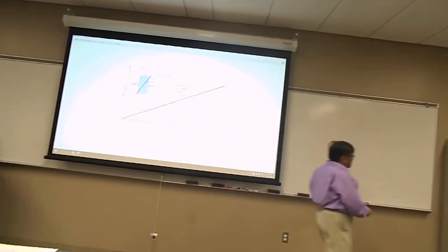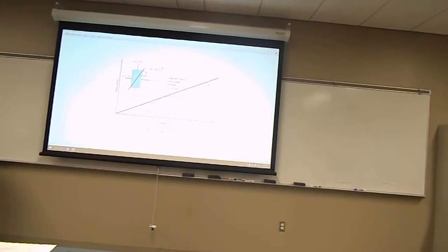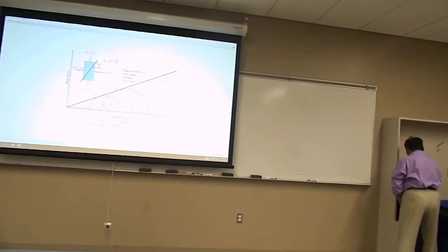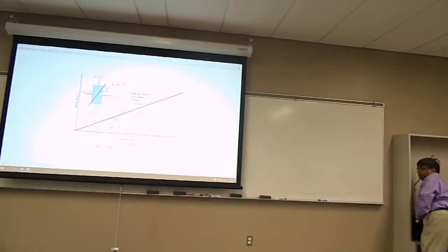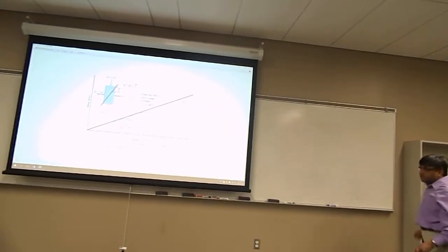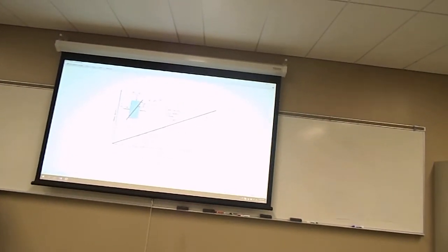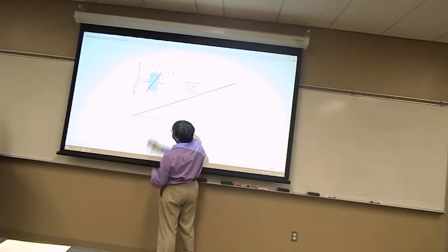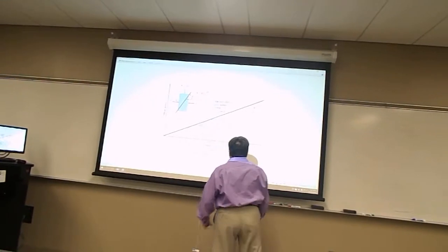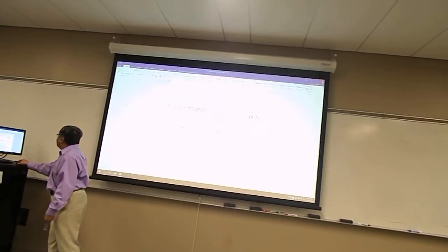I will take a minute to get a straight edge. So, after drawing 2 circles, you can take a straight edge to draw this envelope to get C and phi prime. That's what we do.